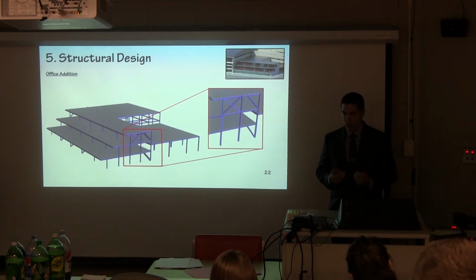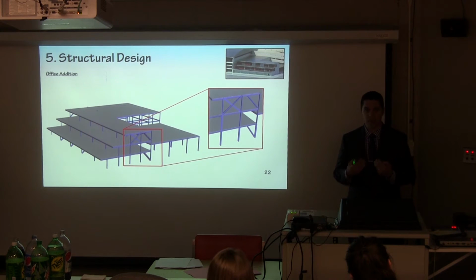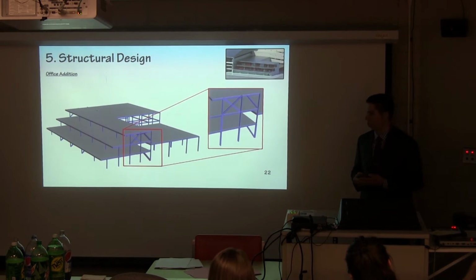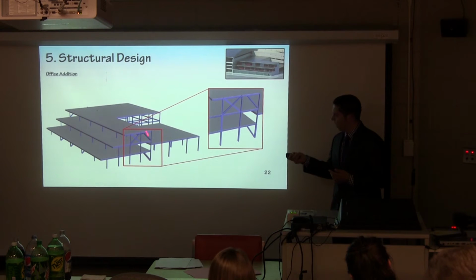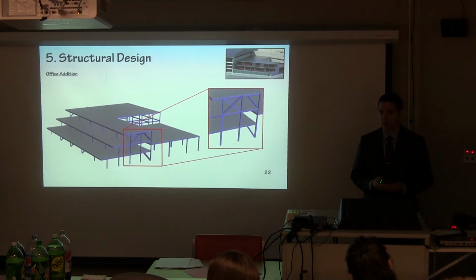A problem that we had here was with the deflection from the wind loading. We only needed to put a very little bit of wind bracing there, and that fixed the problem right away.